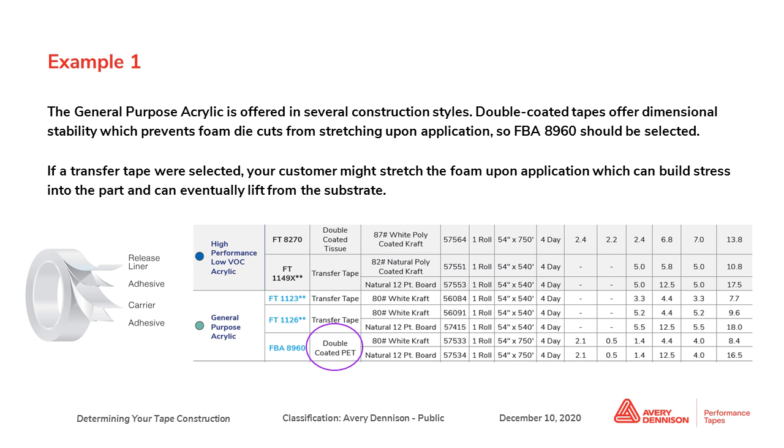The correct answer, because we want to stay within the general purpose acrylic because the customer likes that adhesive's performance, we just wanted a double-coated version of it, right? You want that carrier for dimensional stability.